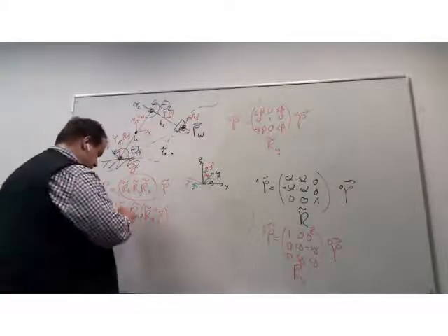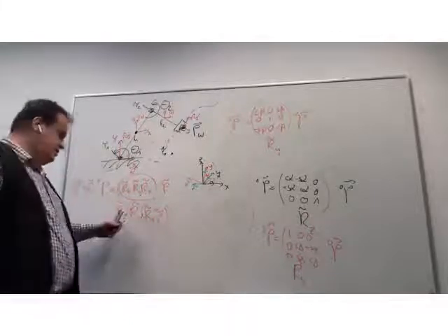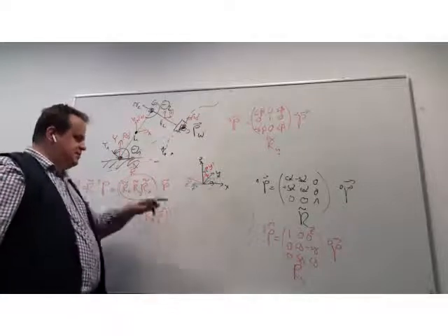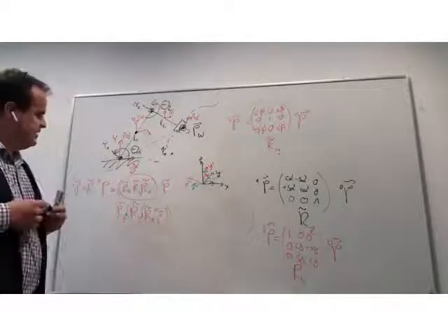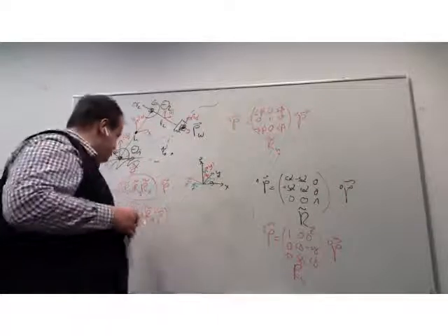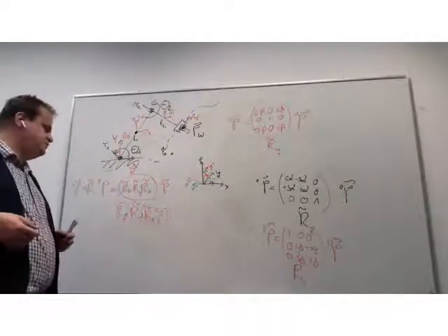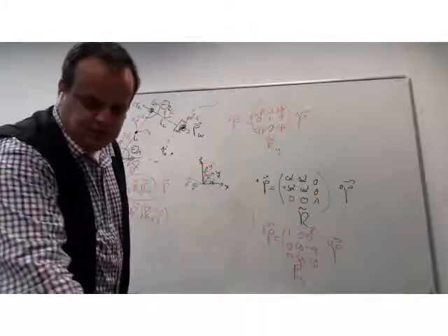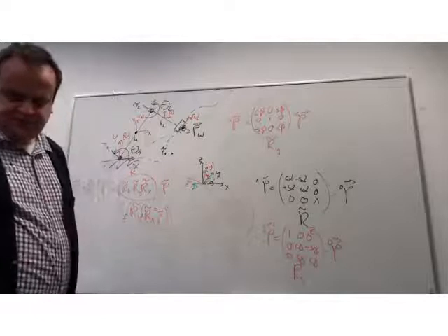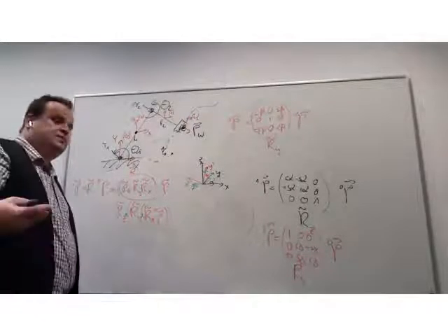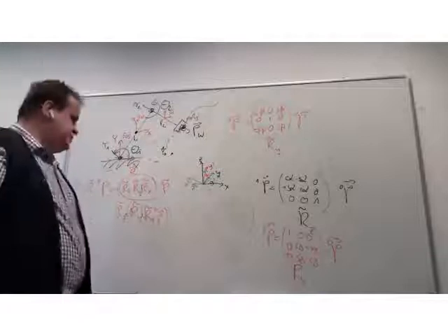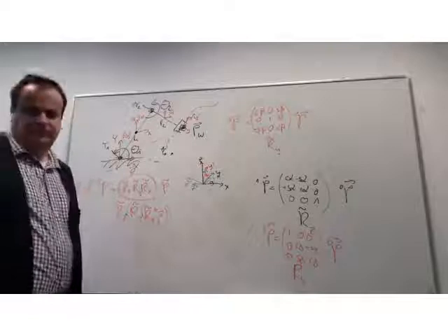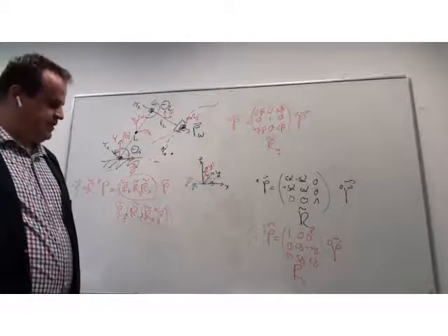And the resulting z rotation is not the rotation around the original z here, but it's around the resulting z after applying the rotation twice. But still, this gives us a way how to decompose the 3 by 3 matrix coming from some sensor navigation system into the three alpha, beta, gamma angles defining orientations around the axes.